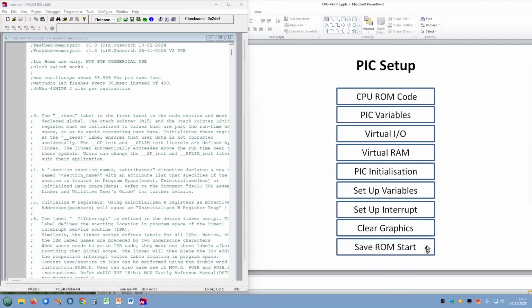And then we'll find out where the ROM lives. The ROM data is held in with the microcontroller code, but it isn't actually part of the program the microcontroller runs. It's just using its ROM to save our noughts and crosses ROM. So we have to find where it is and remember that. We have a look at the code for that.